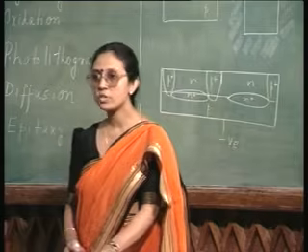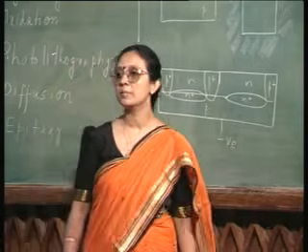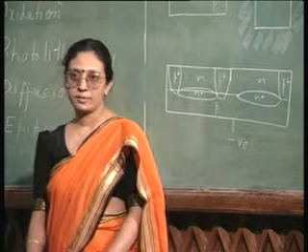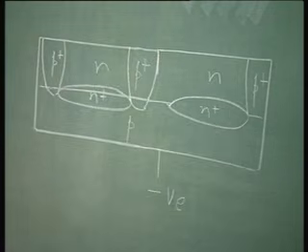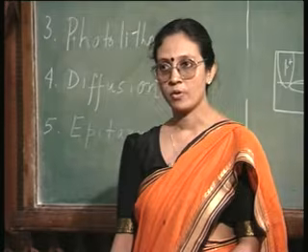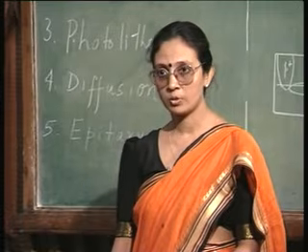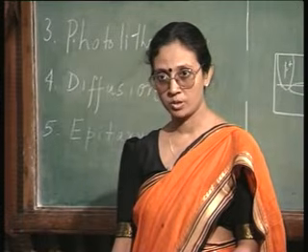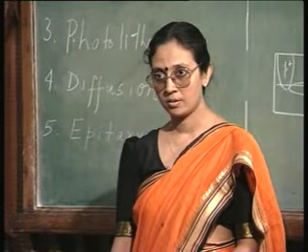I have of course drawn it very simply, but you probably appreciate by now that in order to selectively diffuse these P plus regions, I must have oxidation, photolithography and diffusion, right.